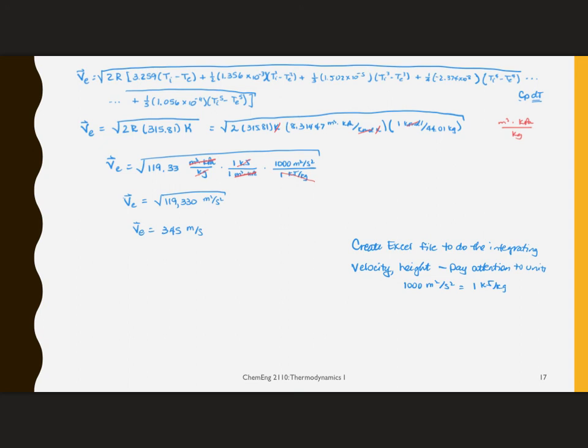And I guess then my final thing is that when you are doing the integral of C sub p dT, it is not the same as saying C sub p times delta T. This is one of the places that people frequently make mistakes. I guess the last place that people make mistakes before I move on is that don't forget to do the square root. At the end, when you're doing the calculations, I've so often seen people who wrote it down, but when they gave their final answer, they forgot to do it.